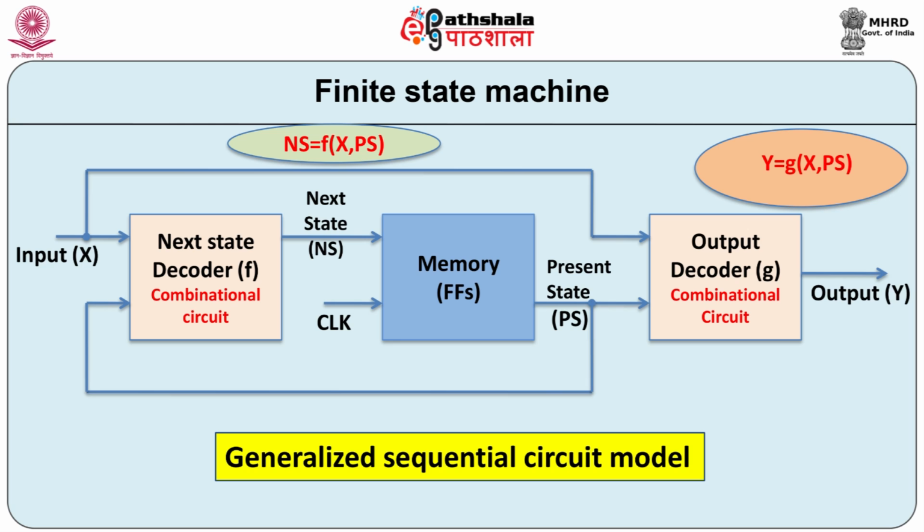As the generation of next state and present state is a continuous process, present state information is fed back to generate the next state with the help of present inputs. These present input conditions are also forwarded to the output decoder through a feed forward path. These inputs with present state generate the necessary control signal at the output of the state machine.